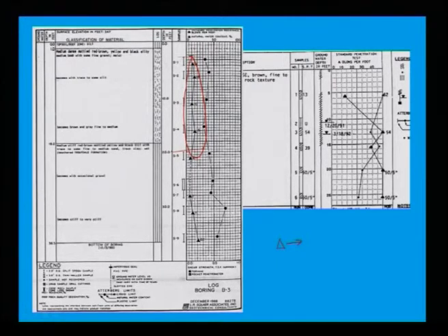Look here, silty sand is available from 2 feet to around 18.2 feet, and it confirms your SPT value. If there is any mistake either in soil classification or in SPT, you can confirm by seeing this profile.